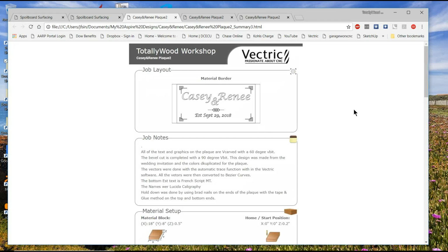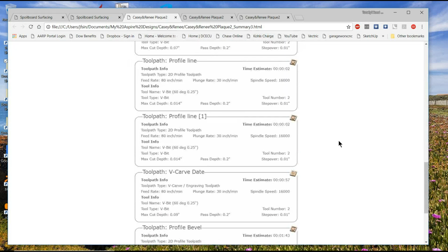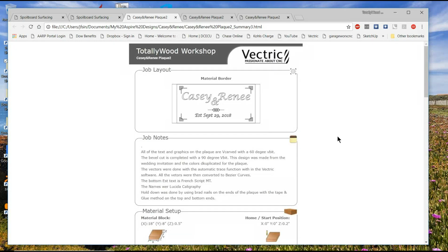For instance, you might start out at 100 inches a minute. If I started at 100 inches a minute and I'm cutting too deep and I see some chatter, I'm using Mach 3, so I just reduce the speed. When it's not chattering, because I forgot I'm using a different wood, then I mark down that I'm not at 100 anymore, I'm down to 60. So I write 60 on this paper, and then I'd go make some new job notes for that particular wood. It's all what you want to do. It doesn't limit you, it just gives you the starting guideline for your job, right?